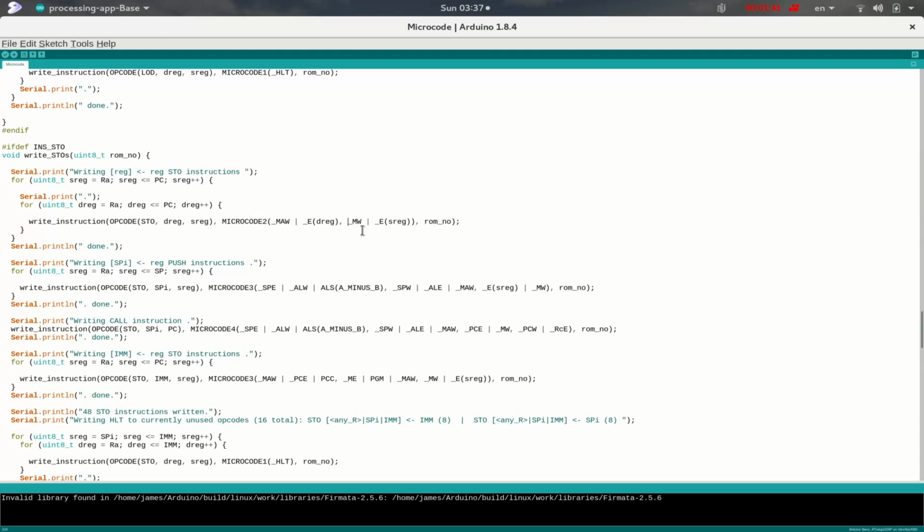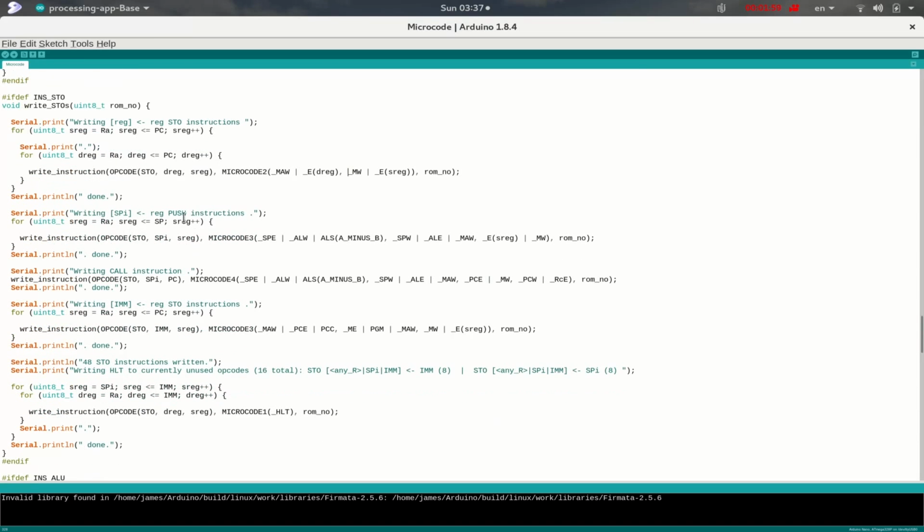And so the only way to ever write anything in program memory is to manually use the dip switches and this programming toggle switch, which we have. So we don't support modifying anything in program memory. Now again, we'll come to the push instruction in a little while, because just as the pop instruction, it's a combination of a memory operation and an ALU operation. And so we'll have a look at the ALU operations first, and then come back and look at the pop and the push instructions.